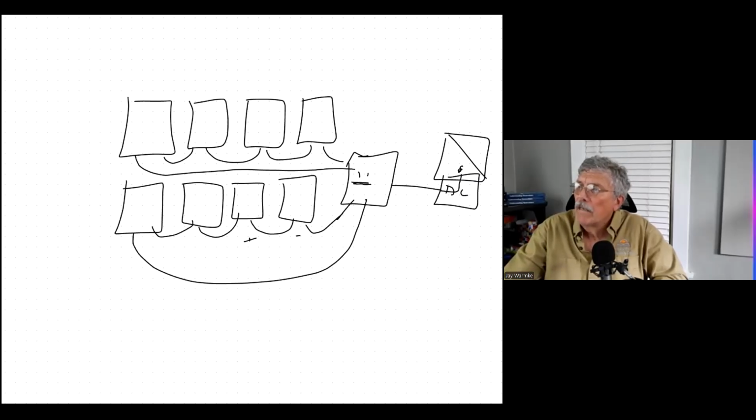So if this panel suddenly gets shaded, that's going to affect all 8 of these panels, because it's going to draw down and it all behaves as if it were just one panel. That's the downside of having a string inverter in a combiner box: if one panel is affected, it affects all of the panels in the array.